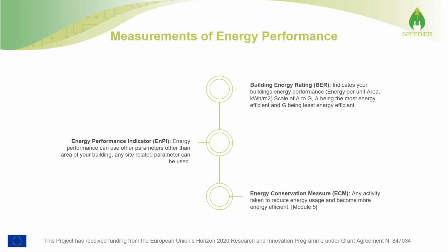Secondly, we must understand energy performance on your site. We can see these every day in the case of BERs, or building energy ratings, for residential houses in Ireland. The energy consumption of your site is not enough to start understanding your site's energy profile. A performance indicator is needed. This can be anything from the area of your building to the number of people in your building, and simply dividing the energy consumption by your performance indicator. And just to note, the definition of an ECM is there at the bottom, and will be covered again in Module 5.